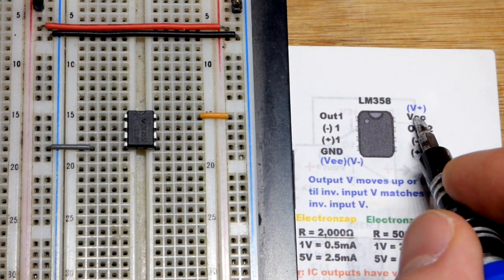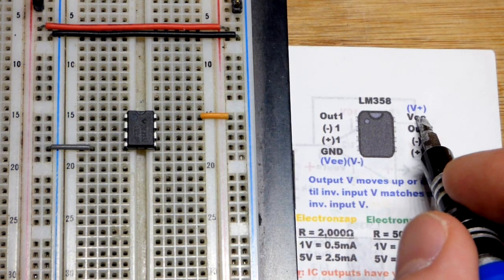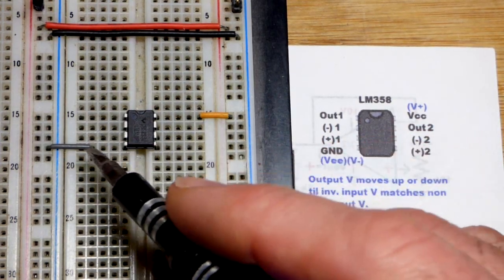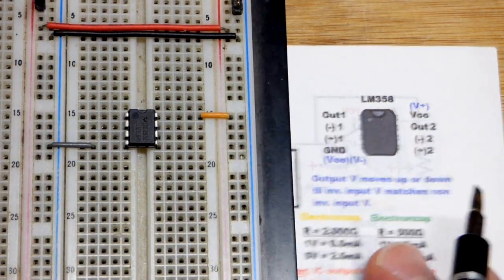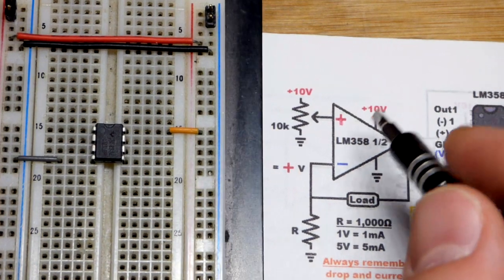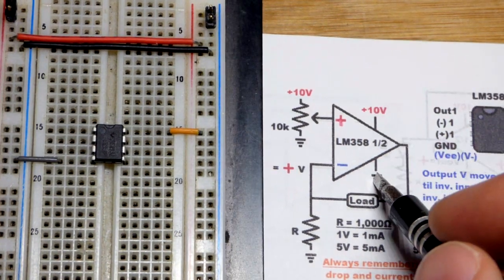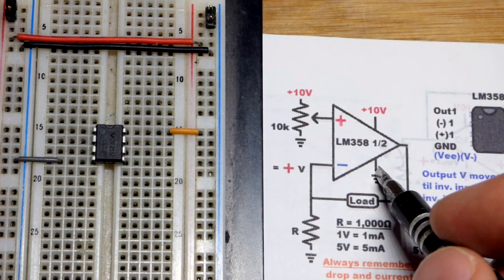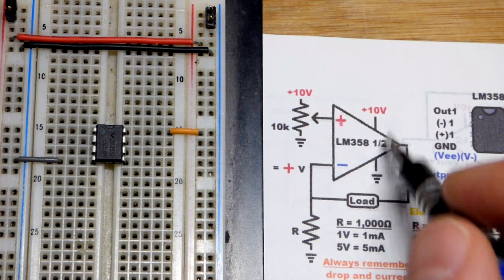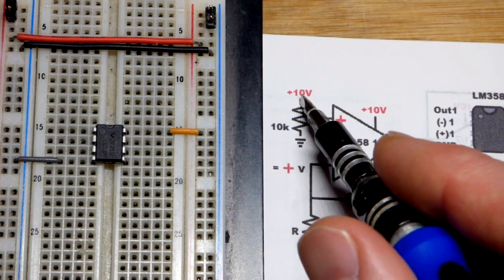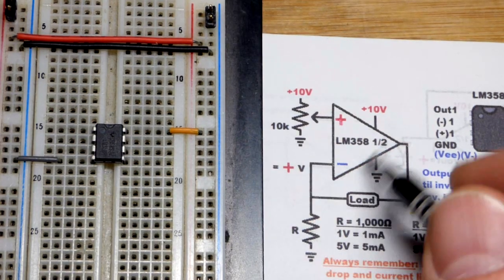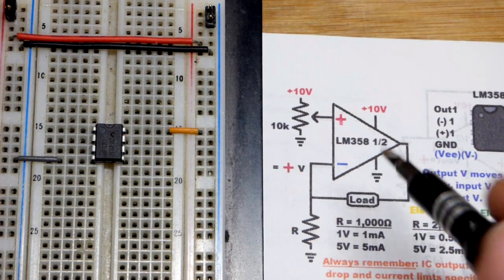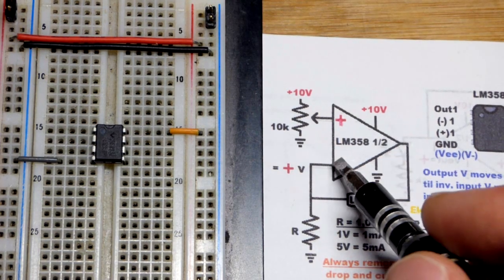We have to power the integrated circuit. So positive supply to pin 8 right there. Negative supply to pin 4. I already did that. So that provides power. In the schematic here, I showed those power pins being powered right there. That's usually where it is lined up on there. You may not see that at all, but looking at the other voltages involved in the circuit, you can pretty much figure out what voltage you gotta power it with. But you always gotta wire it up even if it's not on the schematic.